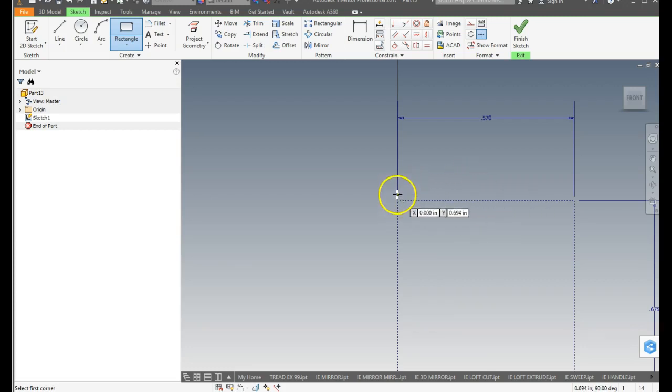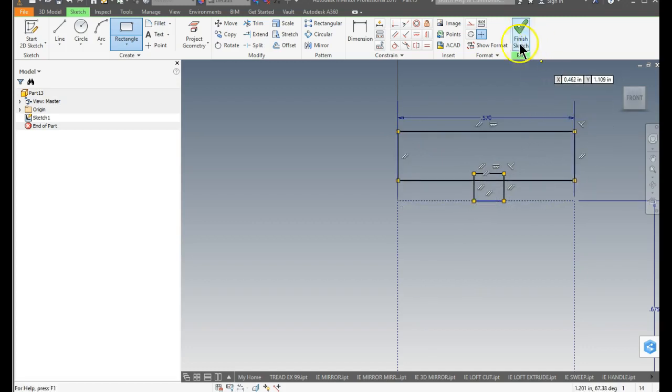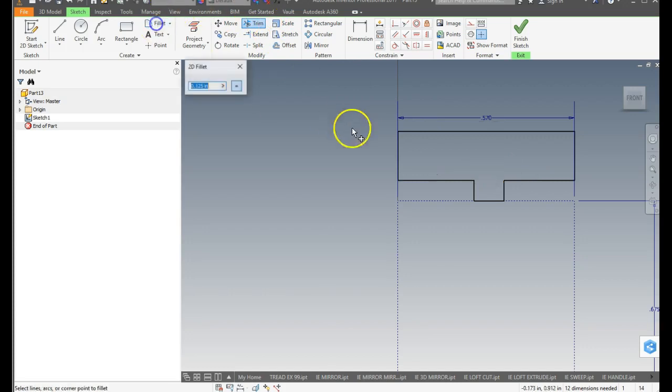If you look at the inside of the tire, you'll see that it has a little kind of spline around the center, so we're going to establish that with a little rectangle. And then I'm going to put another rectangle above that. One of the things you would need to pay attention to is this clearance between my construction line and the bottom of that larger rectangle needs to be the same as the edges of your rim.